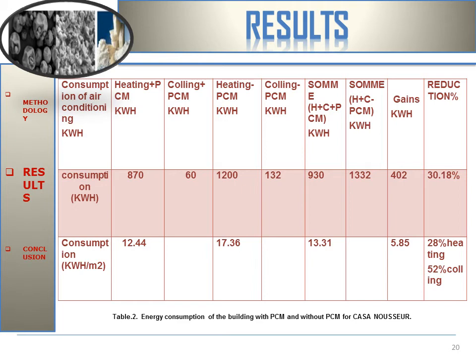Agadir has the highest consumption during the cooling period. The energy consumption with PCM in Agadir was 33 kWh and without PCM 41 kWh. The results show that the presence of the phase change material in the building envelope achieved energy saving by reducing the winter heating period load.